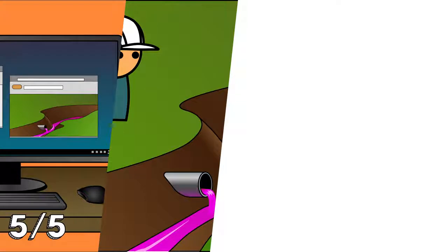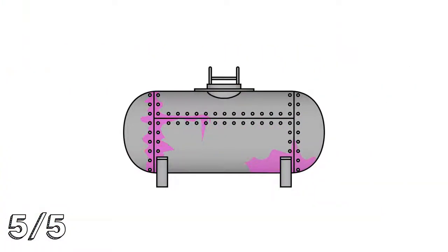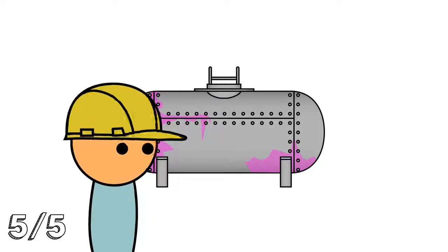Finally, there may be occasions where you have conducted your environmental assessment and determined that contamination is unlikely at your site, only to discover an old oil tank or some other contamination at the site when you are installing your green stormwater infrastructure. If that happens, you should immediately consult an environmental professional to discuss your responsibilities and next steps.